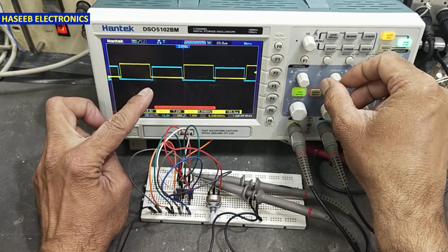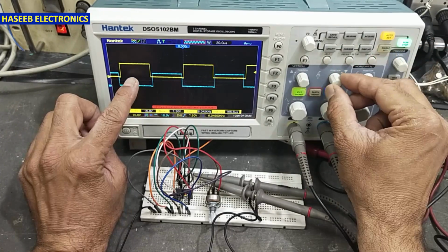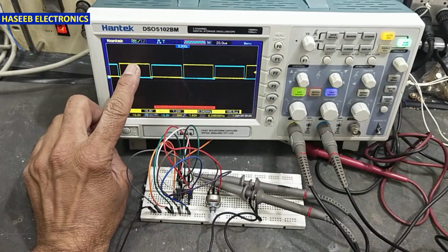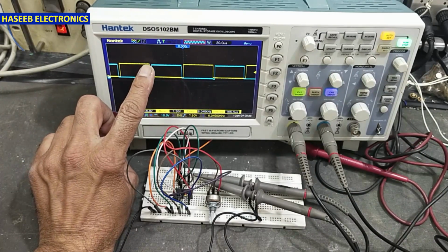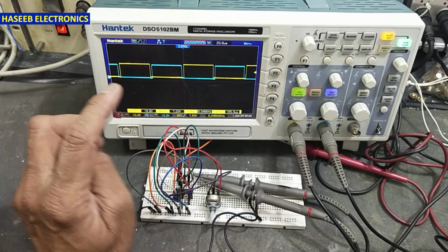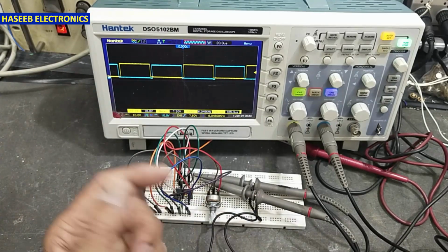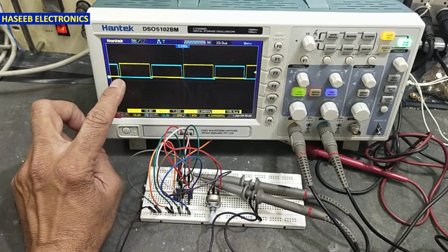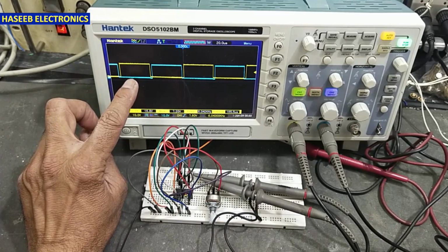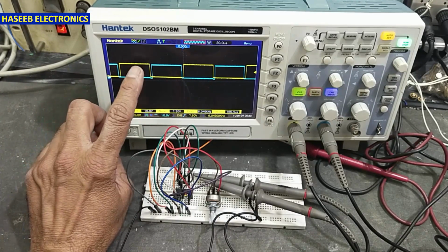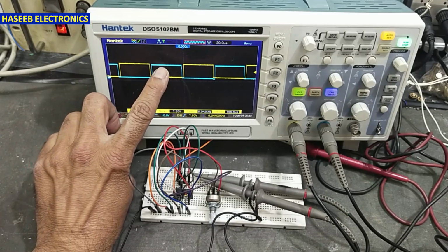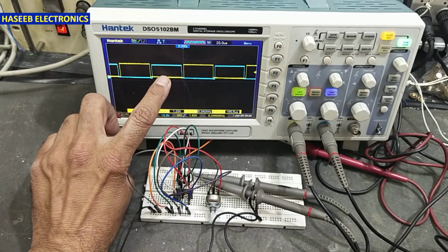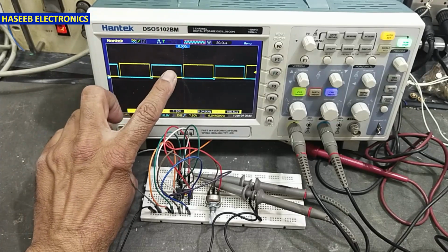Now we can see more clearly. This is our one transistor, the yellow one. It is high. It is giving switched voltage from the emitter. I am taking output from the emitter. You can take it from the collector or from the emitter. If you want to take it from the collector, at that time you need to connect a pull-up resistor to positive, and this is low. When the second channel is high, the first channel will be low. Both channels are opposite to each other.